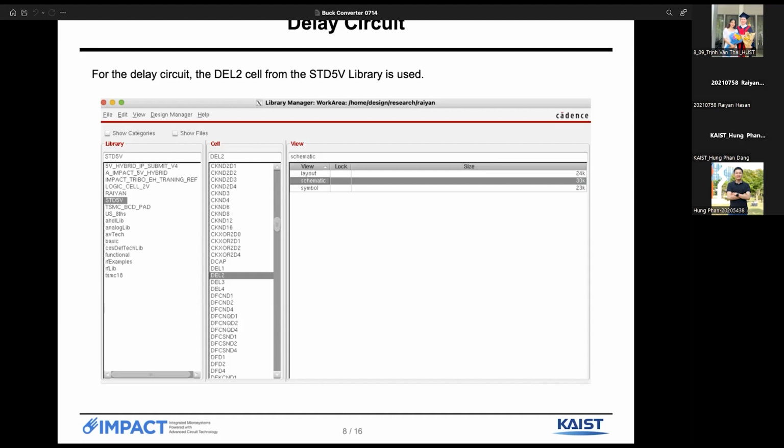Because in here your VDD is 2 volt and the threshold voltage of a 5 volt MOSFET is lower than 5 volt. So in here you use the 5 volt library, but it still works well. However, the power and the delay might be different. So let's change to the 2 volt logic cell library. I will change it in the next week.